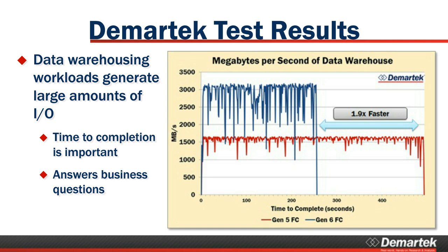Another question is, if you could take a minute and talk a little bit about forward error correction. Is that a new feature, or what's different in Gen 6? So forward error correction as a technology has been around in the electronics and signaling industry for a while, and it is primarily applicable for high-speed interconnects. For example, 25 gigabit Ethernet or 100 gigabit Ethernet requires forward error correction technology, just because at that high rate there could be possible bit errors within the frame. At the same time, 32 gig fiber channel technology as a standard requires forward error correction.